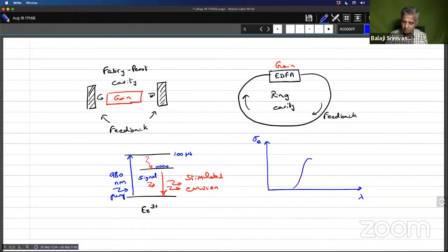And of course, in erbium doped fiber amplifiers, we say that the emission cross section is something like this. It becomes significant around 1520, and then it has got a long tail over here, but somewhere around 1560, it starts going down. So yeah, that's what we are interested in. We're not interested in the pump emission cross section, which actually, by the way, is very low.